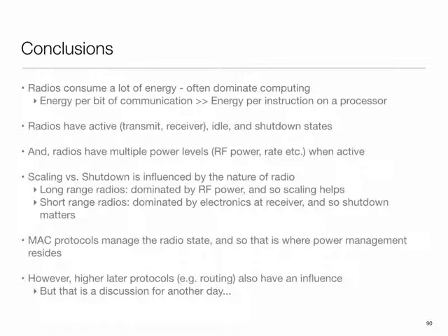And the main concepts that we see: duty cycling is one, and how you can adapt the duty cycle. The other is letting the transmitter send out a long packet chain or a long preamble, and the receiver waking up and sampling the channel, which is called LPL, or low power listening. Preamble sampling is another term which is used for it. Then the third concept we saw is receiver-initiated, which has some advantages. And finally, this notion that packet collisions can be managed. If packets are very tightly time synchronized, then we can still recover from the collision.